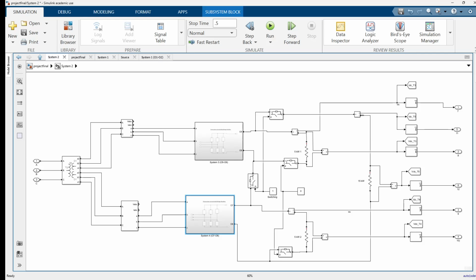Now, why did we use the power semiconductor? All the rectifiers use 600 volt rated power diodes and SCRs connected in series to withstand the required peak inverse voltage.